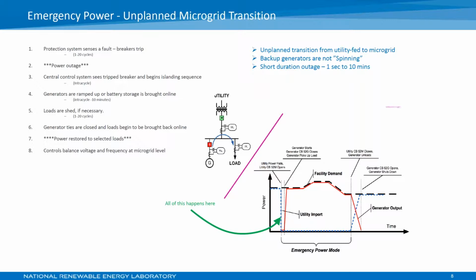If it's a manual thing, a number of electric linemen and technicians would be dispatched, open a number of switches to make sure that the area you want to operate as an island is isolated. They'll be dispatched to start bringing the generation online, also opening switches to disconnect some loads so that you have enough generation to meet the loads that you need to operate during this outage, this islanded or isolated operation.